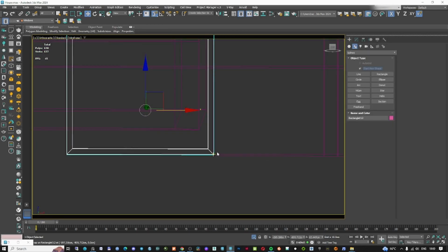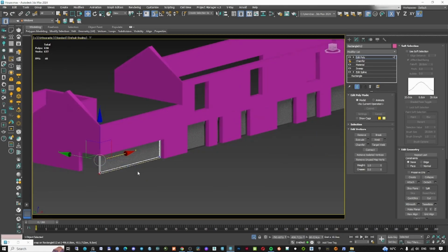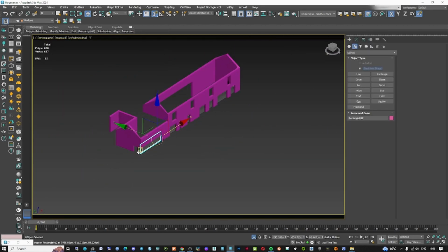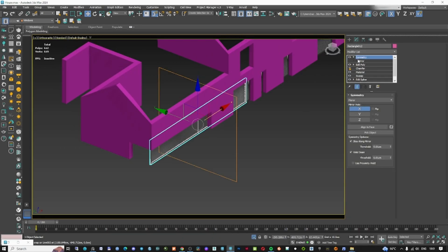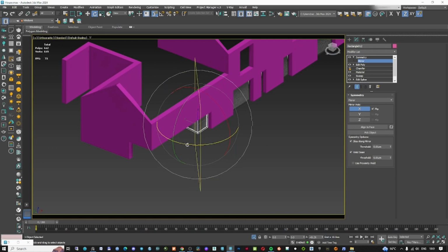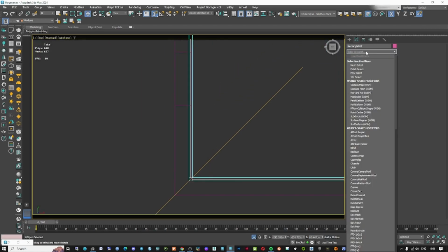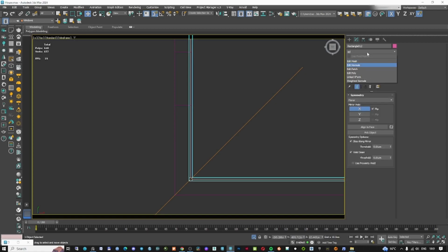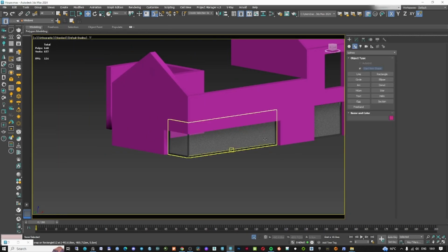And here on the corner window, as you can see, I'm just gonna extend my frame until the corner of the wall. And after that, I'm gonna apply a symmetry, and I'm gonna turn this symmetry to 45 degrees. In this way, I'm gonna have a corner window in that place. Of course, one side after I did that is going to be longer, but I'm gonna apply an editable poly over, and I'm just gonna make it smaller in that direction.